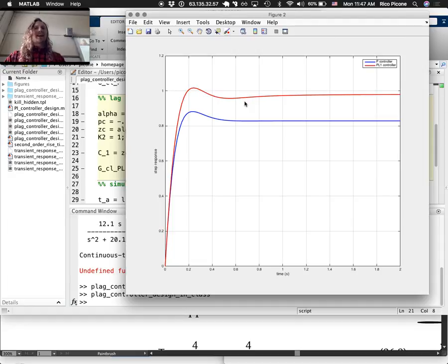Our settling time, there's a little weird thing to observe about settling time. Typically, the definition of it gets really messed up when you use this slow steady-state error compensation, using an integrator or using a lag compensator, because the definition of the settling time is the time at which the response gets to within 2% of the final value and then doesn't leave it again.